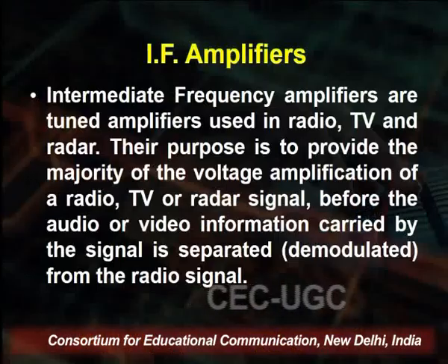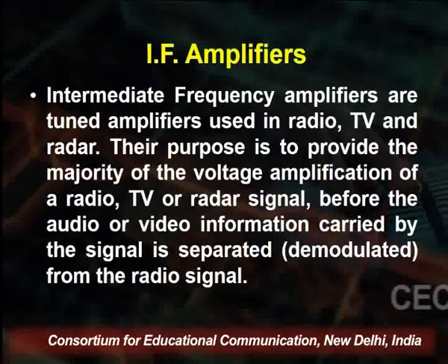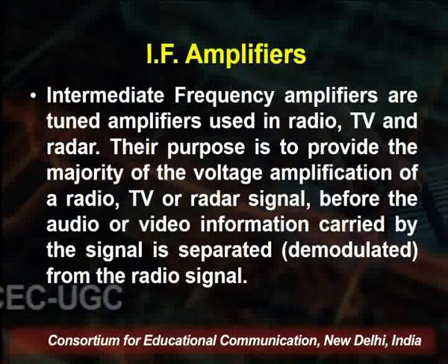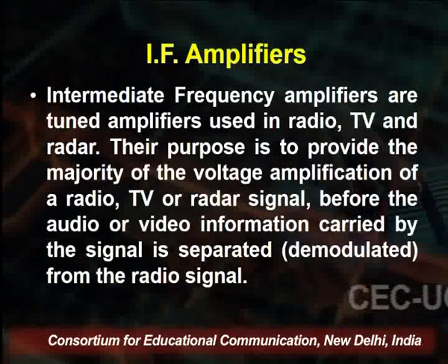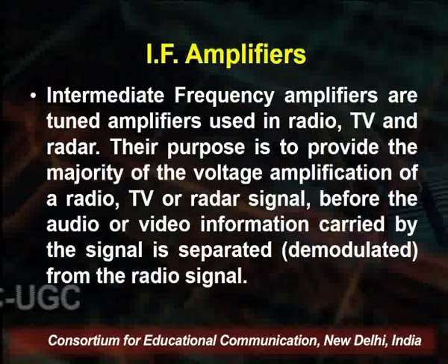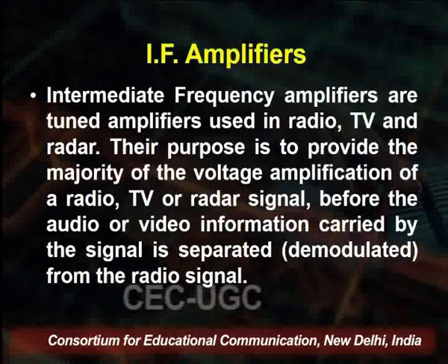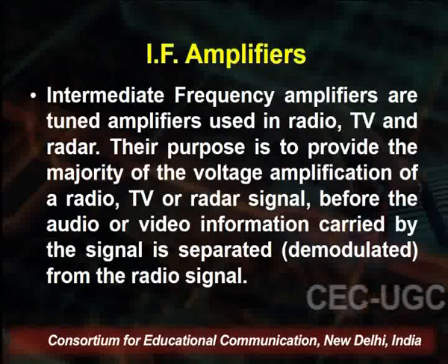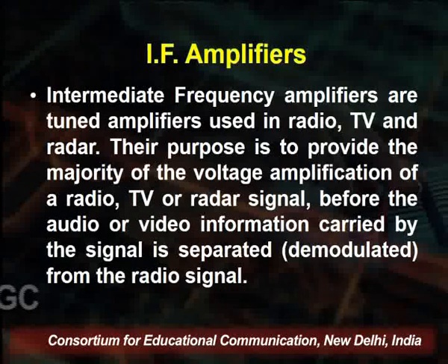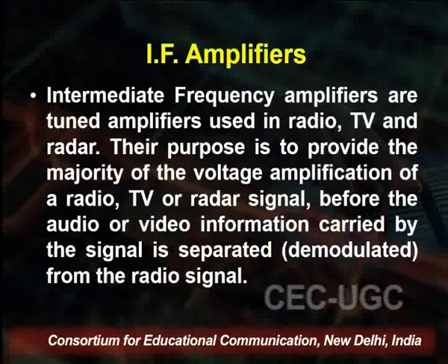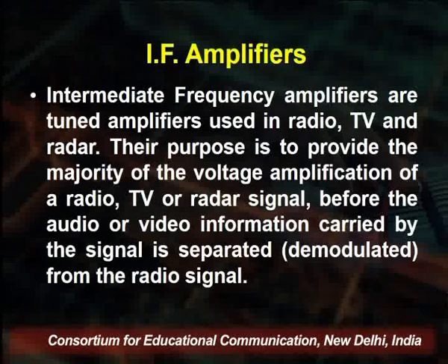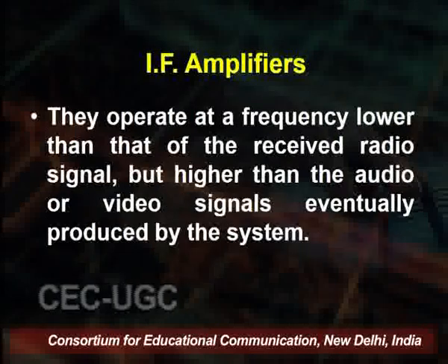Next is the IF amplifier. Audio frequency is where the audio is, to increase the sound. The IF amplifier, which is the intermediate frequency amplifier, is a tuned amplifier used in radio, TV and radar. Their purpose is to provide the majority of the voltage amplification of radio, TV and radar signals before the audio and video information carried by the signal is separated, or demodulated, from the radio signal.